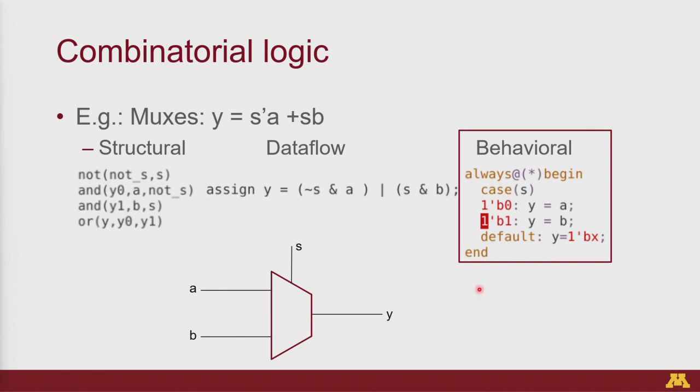So I have to be very careful to complete the case statement. Yes, that's where the default keyword comes in. For example, if this was a 2-bit select line, there can be 4 possible values, and let's say we're only interested in 2 of them. For those 2 values we define the outputs, and then we have a default case to say what the output should be if the other 2 come. In case I do not complete the case statement, will there be an error? It will build a latch.